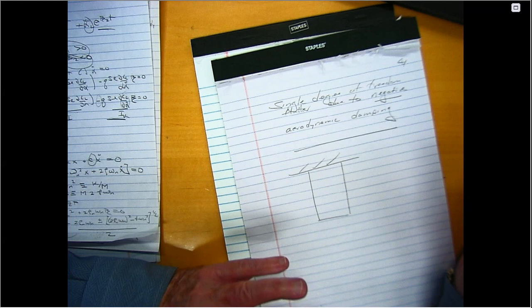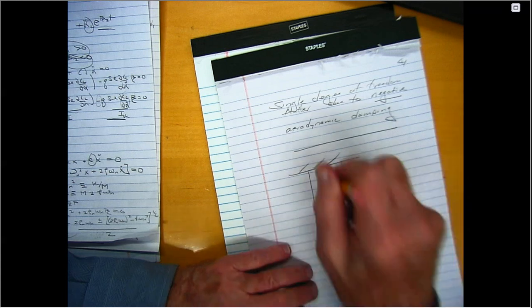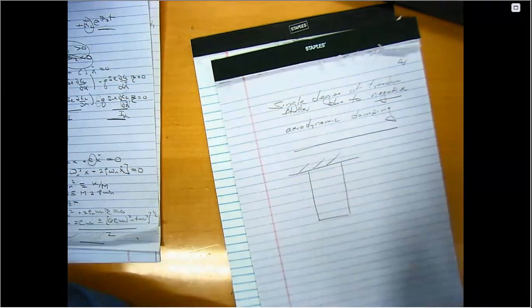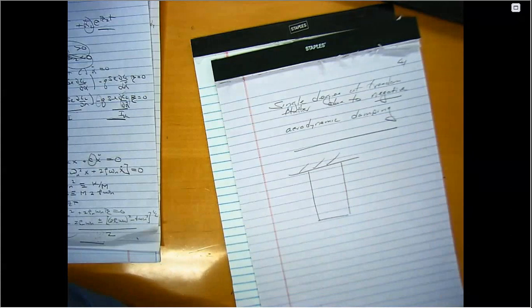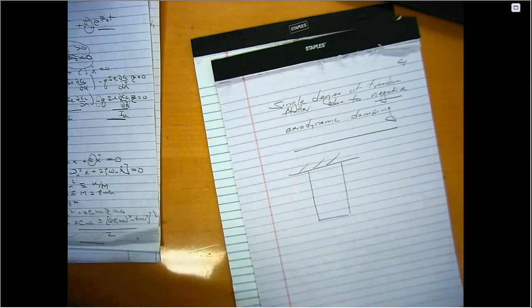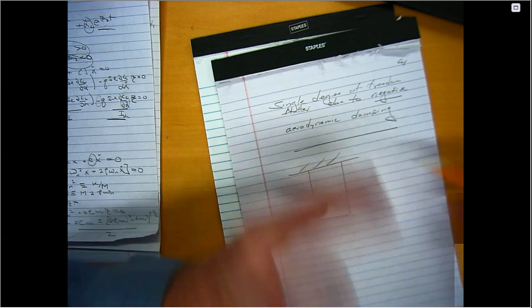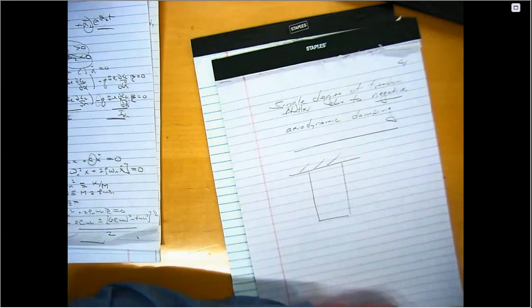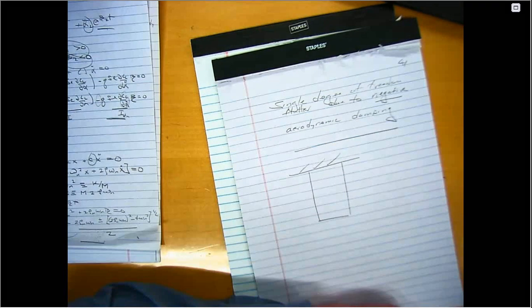And again, it's very much like what we were talking about a moment ago in a slightly different context. It only takes one unstable mode to make the whole system unstable, because if there's one unstable mode, over time that mode will grow in amplitude and all the other modes will decay away, and that will be the dominant solution. So one unstable mode is sufficient to make the whole system unstable. Well, that's a little bit of a complexity. Why? Because even though these systems in principle have an infinite number of modes, you can't check that many, right? So some judgment is required.